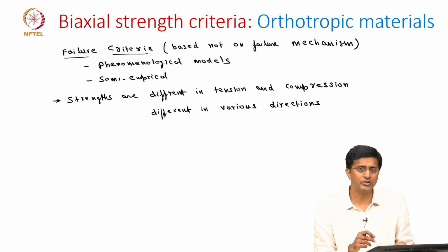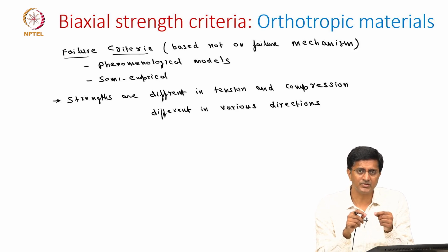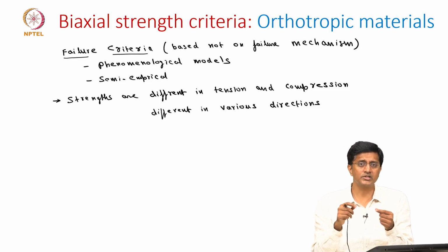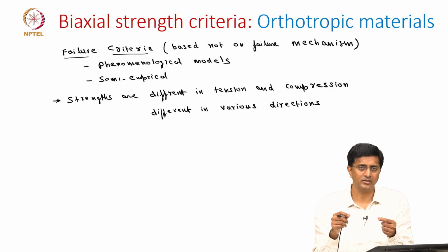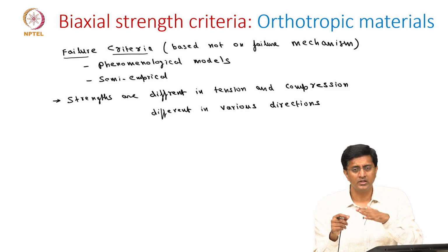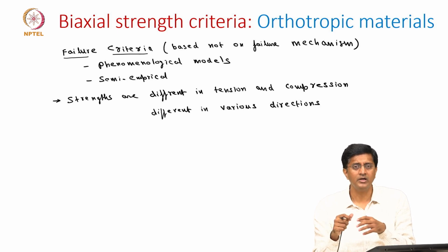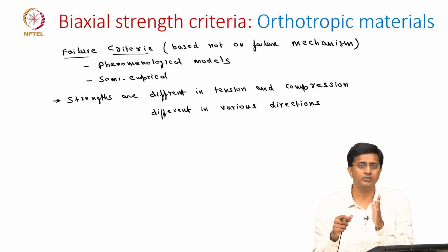But here we cannot do that because let's say the maximum stress is there on sigma 1, which is the principal stress, but then even the strengths along that direction are high. So meaning that though the stresses are high along the direction 1, it might fail maybe in direction 2 where the strengths are low.